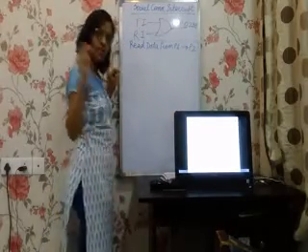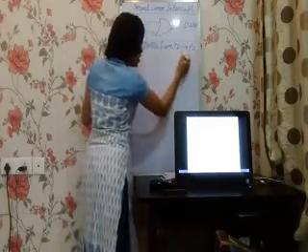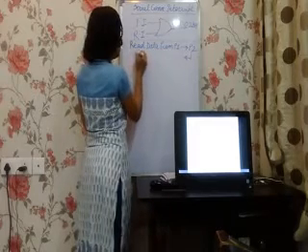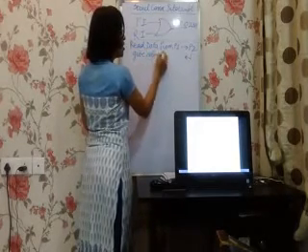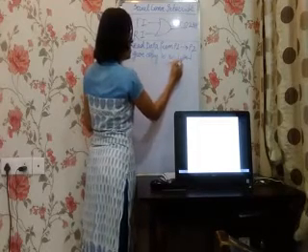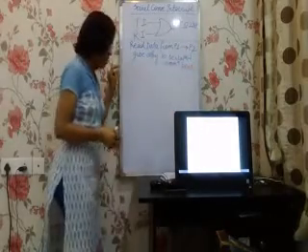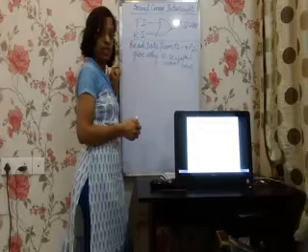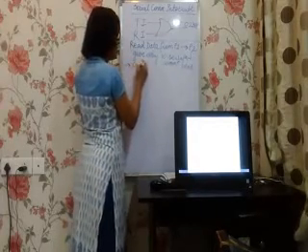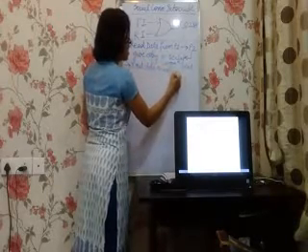This is the first task that the microcontroller has to do. Also give a copy of the data to the serial communication port, so that it can be transferred. Now the data has to be transferred serially, that is, transmit data serially, say at 9600 baud.